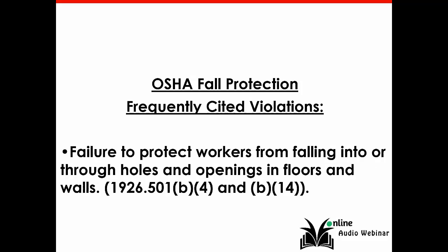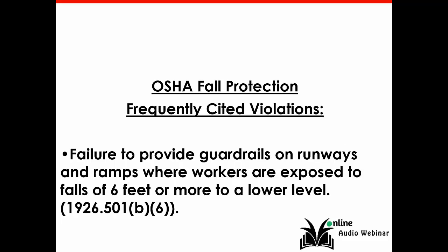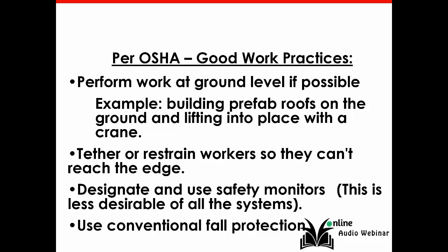Some of OSHA's most frequently cited standards are around OSHA's Focus 4 and fall hazards. Failure to protect workers from falling into or through holes and openings in floors and walls. Failure to provide guardrails or runways and ramps where workers exposed to falls are 6 feet or more above a lower level. So, some good work practices.